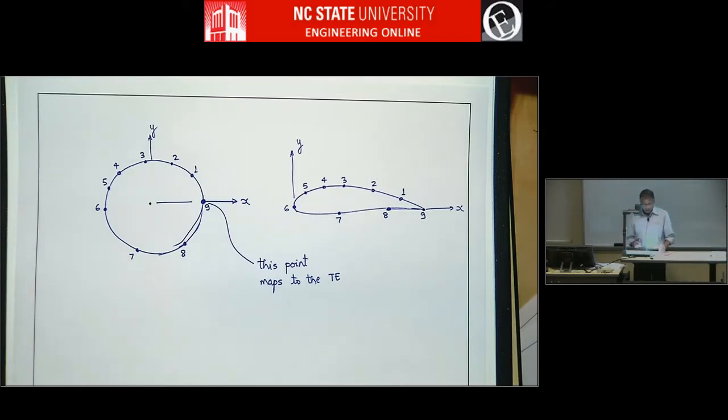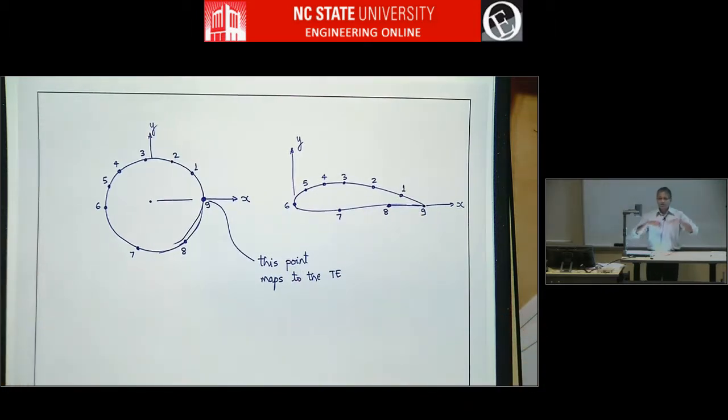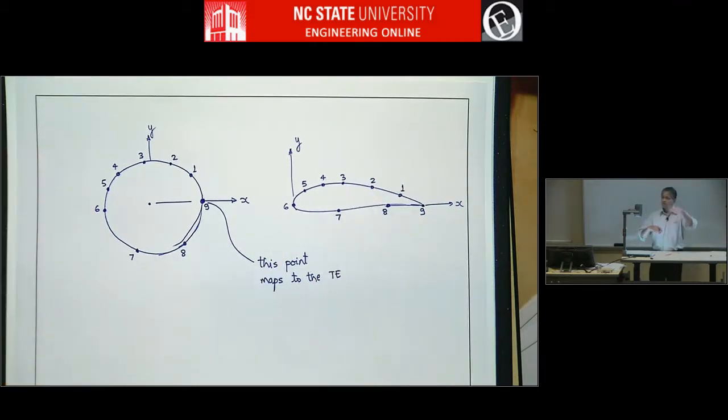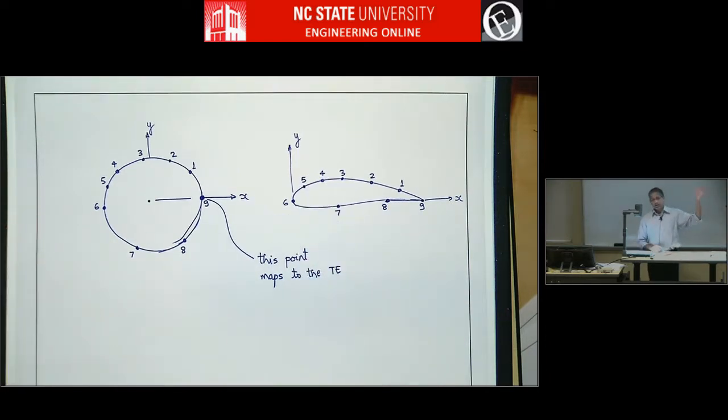So one of the first misconceptions I have to dispel, which is a question that people usually ask in a lecture or two, is that it's not like you have these 9 points and then you somehow draw a spline or smooth curve through it or something like that. No, that's not at all what happens. These are just ways to demarcate the geometry and take each one. So for example, we'll take this part and say, I want some velocity distribution at a lift coefficient of 0.3, something like that. And then this one will be, I want something else at a lift coefficient of 0.8, right?